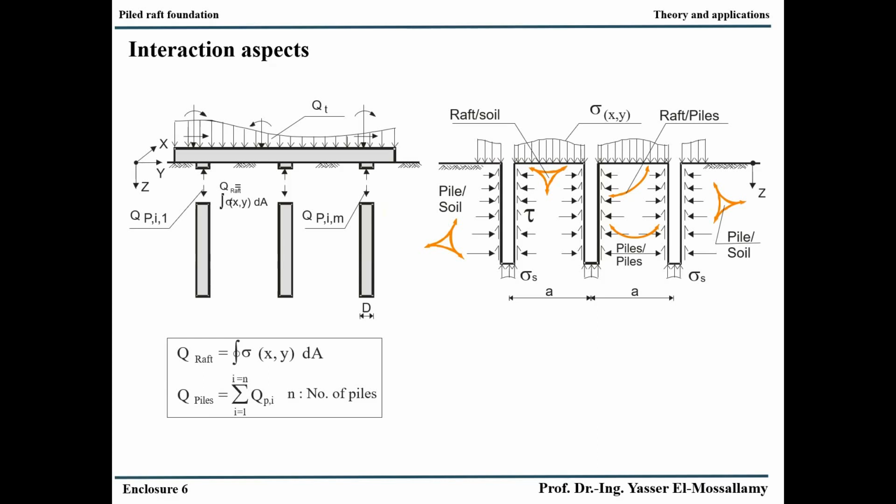The second problem with the piled raft foundation is the codes. Till maybe about 15, 20 years ago, it was not allowed to apply this load part taken by the raft. And in Germany, they have applied the piled raft in the first 20, 30 years on their own responsibility, without codes, without recommendation.